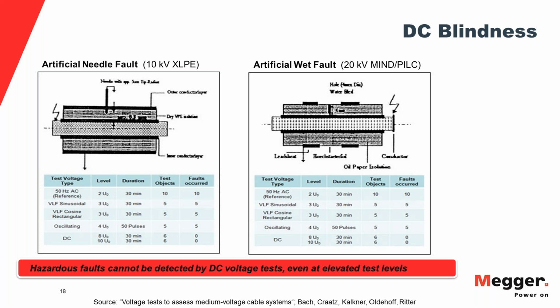And then when you re-energize with AC, power frequency, the cable will fail pretty soon, because in one direction of the polarity you will have over voltages, and then immediately you created a partial discharge weak spot in the insulation.